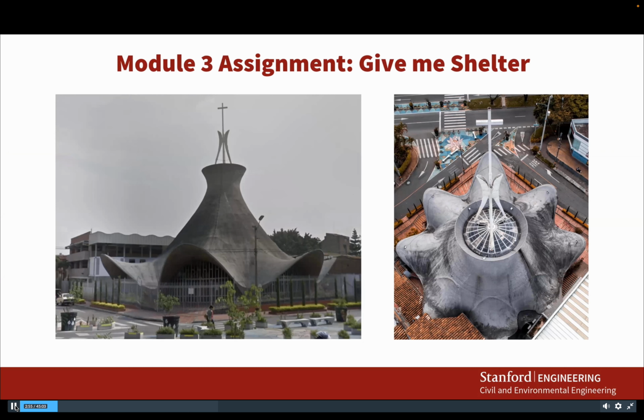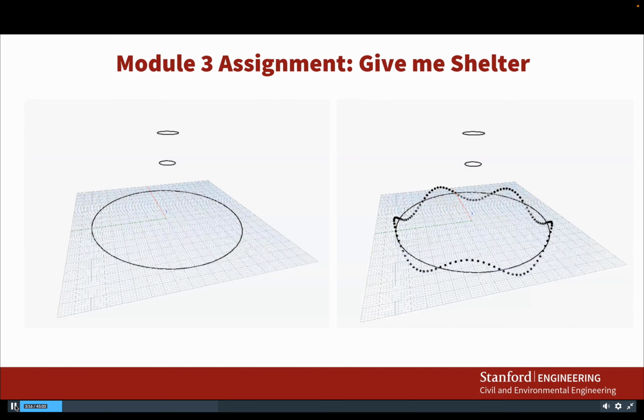If you look closely, this surface is defined by circles. The base circle has a sine or a periodic wave around it, and then the top circle is just a plain circle, and there's a curve in the middle. So the way I thought of doing that in Dynamo was by defining my three circles, and then using things that we've covered so far, such as point at parameter, ranges of points, and sine waves.